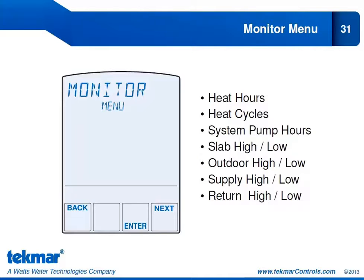The Monitor menu contains a lot of useful information for you to determine how your system has been performing. It will tell you the amount of hours that heat relay has been closed and the number of heat cycles that it has seen. You can look at how many hours your system pump has been running. And then you can look at some trends. What was your highest slab temp and what was your lowest slab temp? Likewise for outdoor temperature, supply temperature, and return temperature. So this can be very useful for you to determine if your system is performing the way you expect it to or the way you want it to.